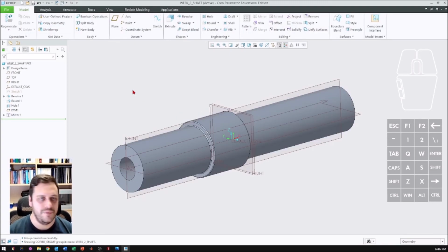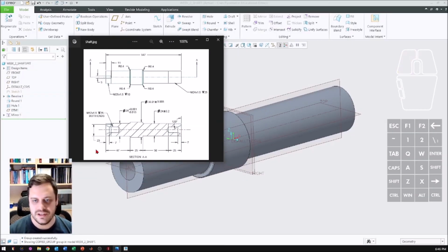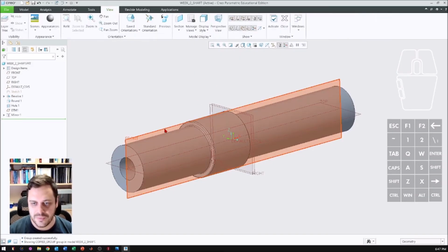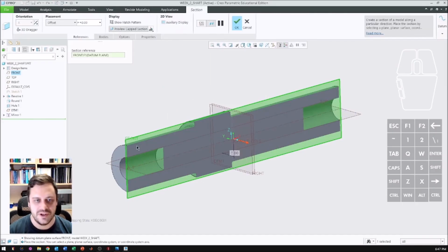So that's what I was talking about before if I bring the drawing back across. This is where we were talking about having the hash section through here, if you like, imagining it was cut in half. And doing section views in CREO is super simple. So if I drag this drawing back across through here, within CREO to do a section view, all you simply do is click on view, click on the plane. So I'm going to use the front plane for this instance that I want it about, and then just click on section. And you'll see that it's chopped it in half.